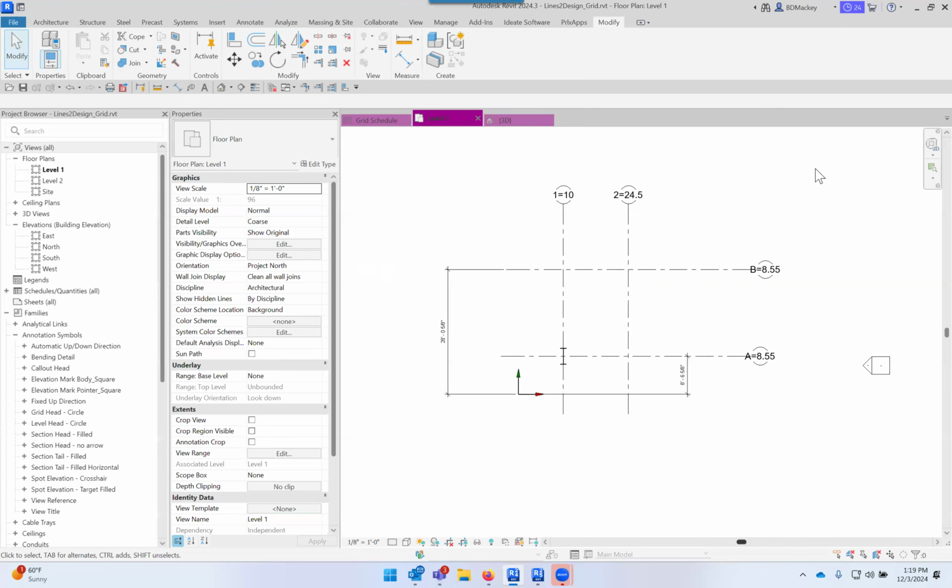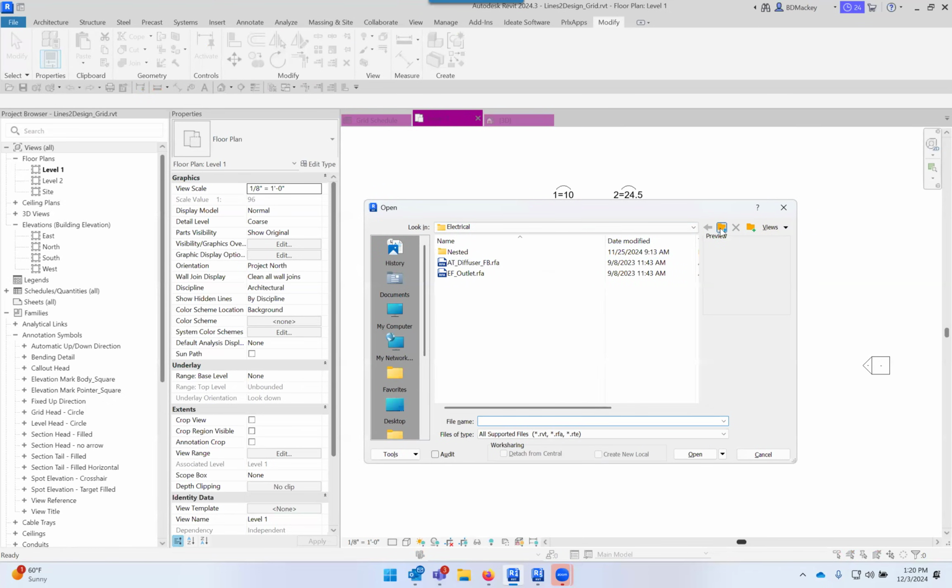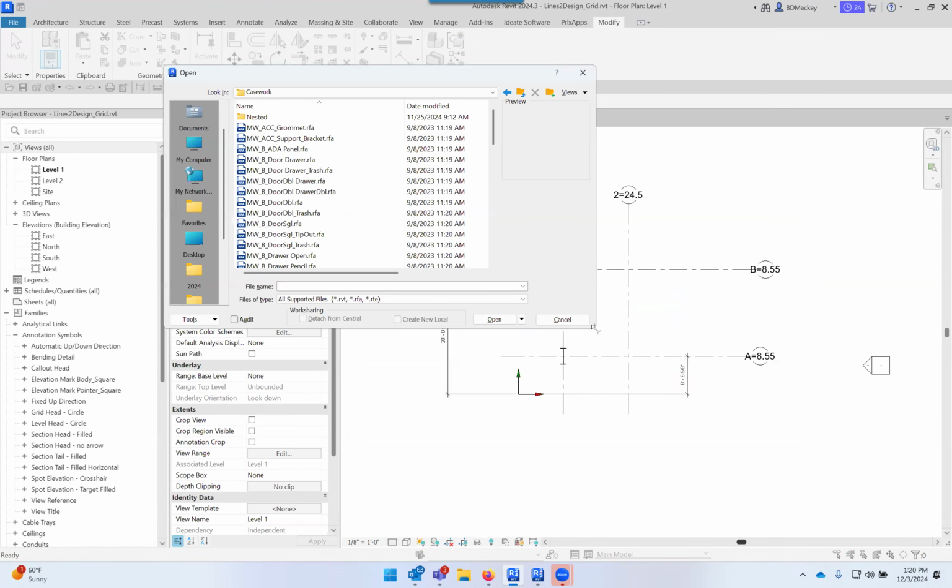And the other reason you're also going to want to do that is especially think if it was something like a pipe or even a rectangle. If I say that rectangle is 3.5 inches, like if it's a 2x4 going up, well, on the ends, it's actually like 5.5. So if you tried rotating the profiles to be plumb and then sweep those profiles along the path, you're actually not going to be 3.5 in the section because it's going to be 3.5 vertically. So personally, for me, I create those families, and it would be similar to my millwork families. I go create all of those families, but I add voids inside of there.